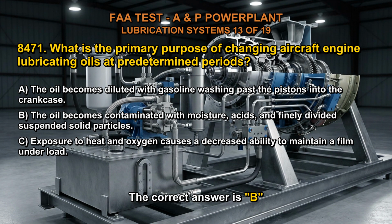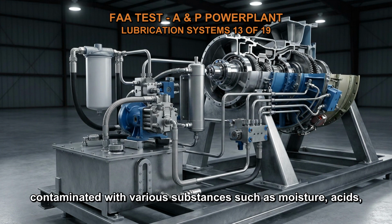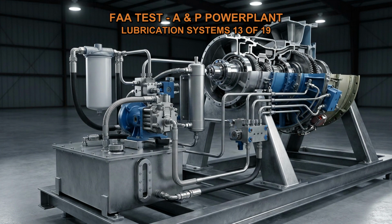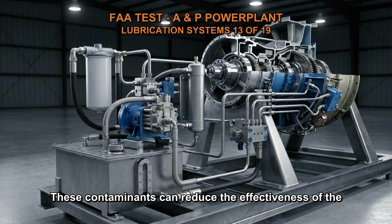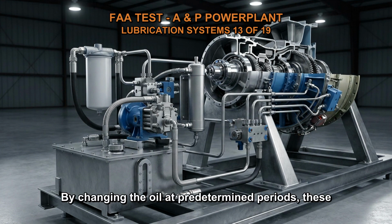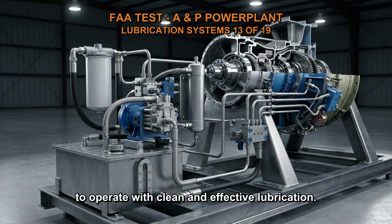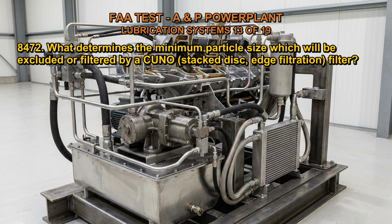The correct answer is B. Over time, aircraft engine lubricating oils can become contaminated with various substances such as moisture, acids, and solid particles. These contaminants can reduce the effectiveness of the oil in providing proper lubrication and protection to engine components. By changing the oil at predetermined periods, these contaminants are removed, ensuring that the engine continues to operate with clean and effective lubrication.